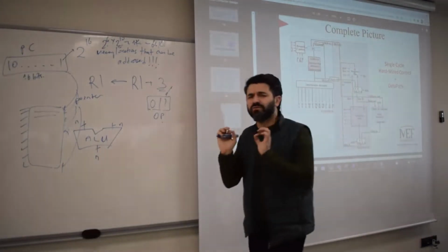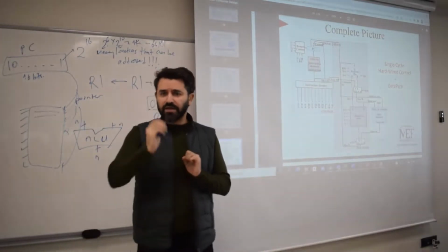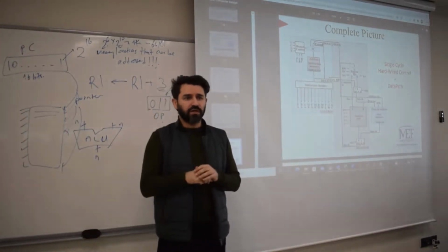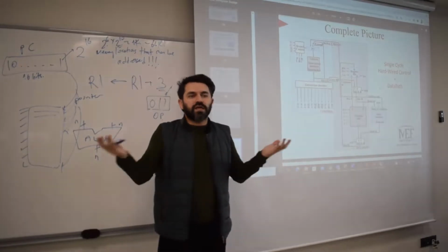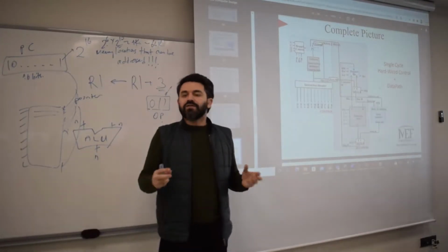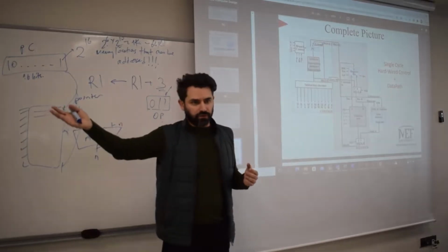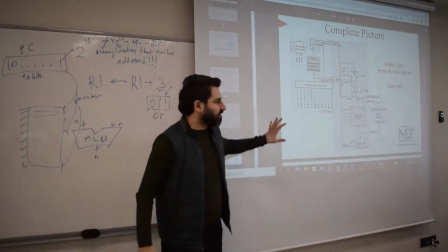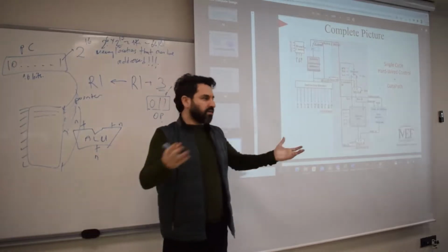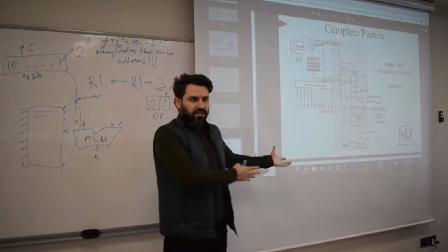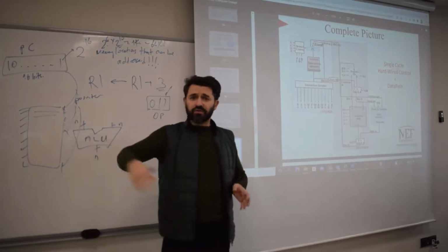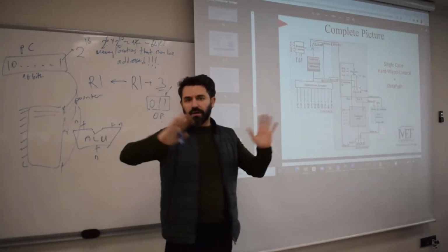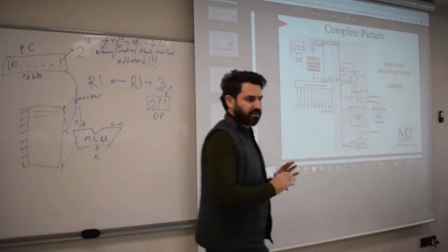Instructions need not finish in a single cycle, and as you know from your project, the add instruction takes 3 clock cycles. The subtraction operation takes 3 clock cycles. So that is called a multi-cycle computer, okay? Since I already had time to discuss single cycle in the class, that's why I put the multi-cycle example in the project, so you learn the maximum possible from this class, okay?